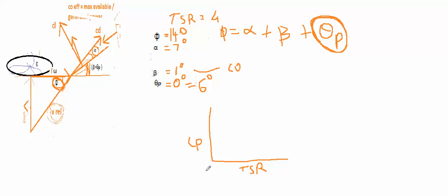Once we get into forces, we will know exactly the amount of force acting on the blade element and the power generated by them. So it will become very interesting. The curve would be something like this. As we change the pitch angle, we can improve the coefficient of power, but we'll get into it later.